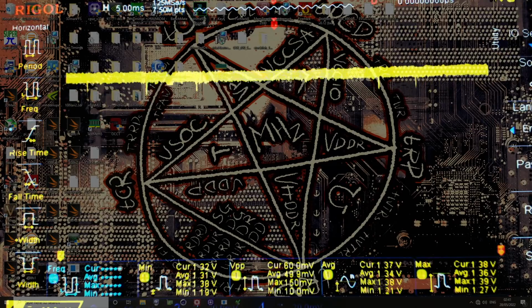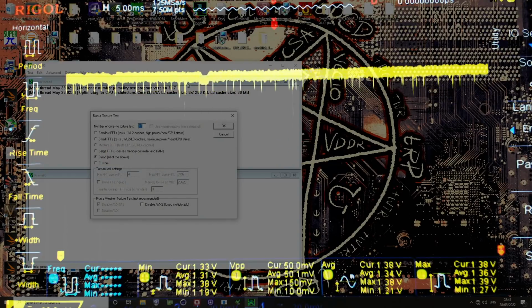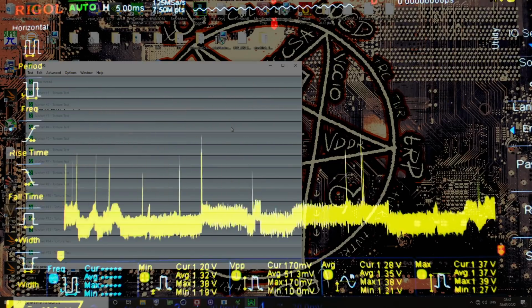And so they just removed the option, which is kind of interesting because on a lot of International Rectifier boards, I'm pretty sure Gigabyte had 300 kilohertz be optimal in the past as well. I think it might just be like Asus and EVGA boards, where changing the switching frequency did nothing. As in, it didn't make the VRM run any better, and it didn't make it run any worse. Anyway, here goes 500 kilohertz.